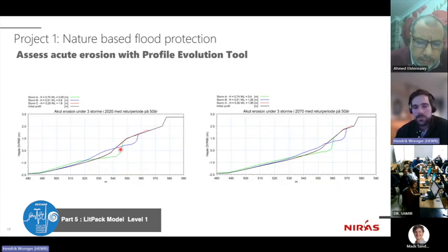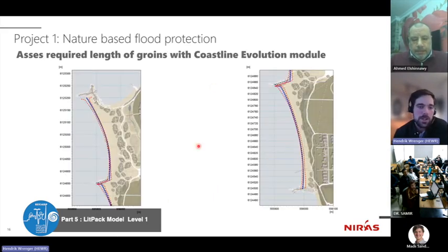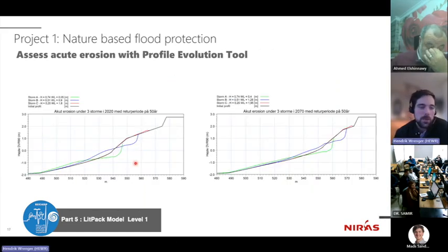So that is why it is possible to model it in these separated approaches. When would it then not be applicable anymore? When would our coastline evolution approach not be applicable anymore? Well, that would be the case if the storms have an impact all the way to lower water, and what is deposited here might not correspond to that anymore.